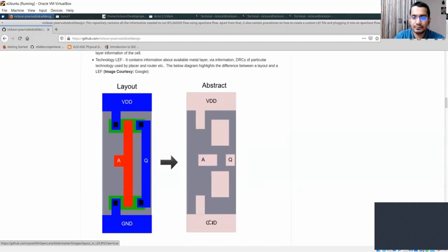You have your first level of interconnects, you drill contact holes. You have your second level of interconnects, you again drill your contact holes. You have a third layer of interconnects that we are going to deposit now. It will look something like this. Okay, and you will use mask 15 now, because this was mask 14. Now this is mask 15 to make the third level of interconnects over here.